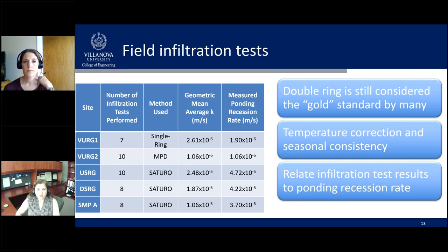With all of these measurement devices, we went out and performed no less than 7 infiltration tests at each site. With these different sites, the little sites within the site were selected somewhat evenly throughout the rain garden bowl, understanding that these are vegetated sites, and so a true grid is actually not possible because you've got plants and trees and bushes all in the way.